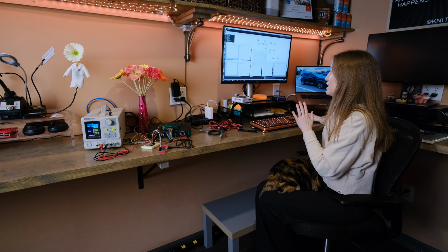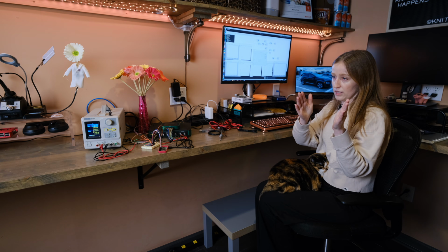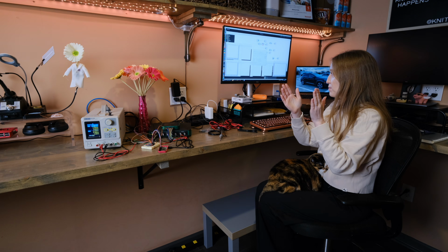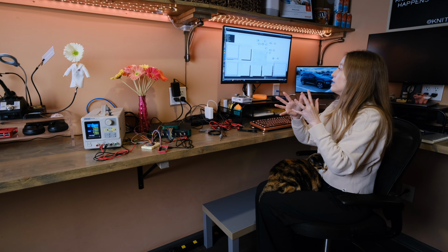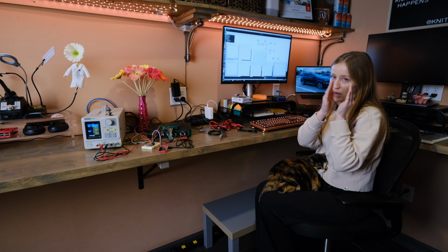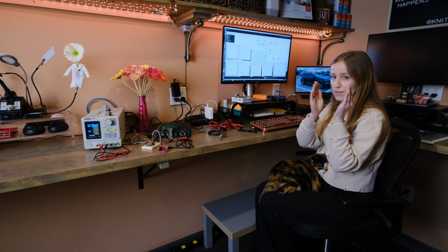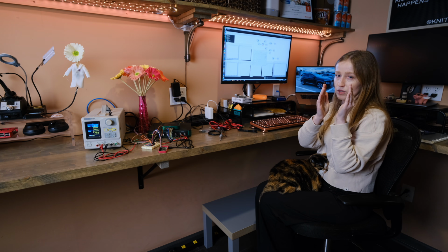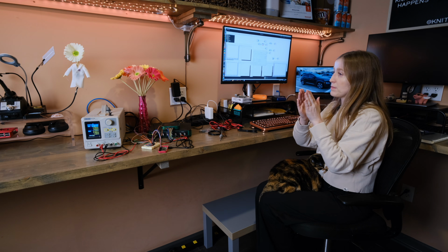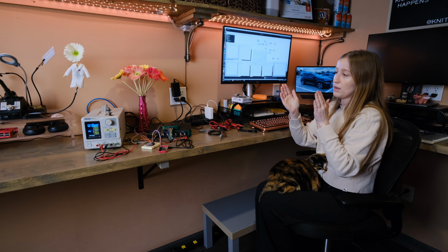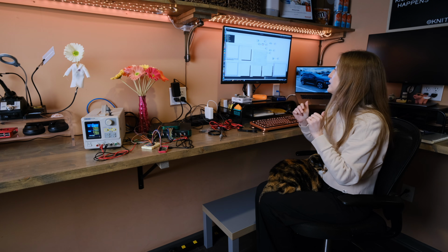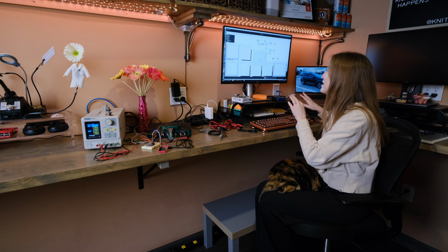As the window of the maximum slides across that spectrum, it's sliding across in a bandwidth of 100 hertz. Obviously, the shorter I make that bandwidth, the smaller the window that's sliding across the band to look. That's going to take more processing time, more processing power, more memory, that type of thing. But if I widen that window, the sweep is shorter and it will be faster and take a little bit less power from a computing standpoint.